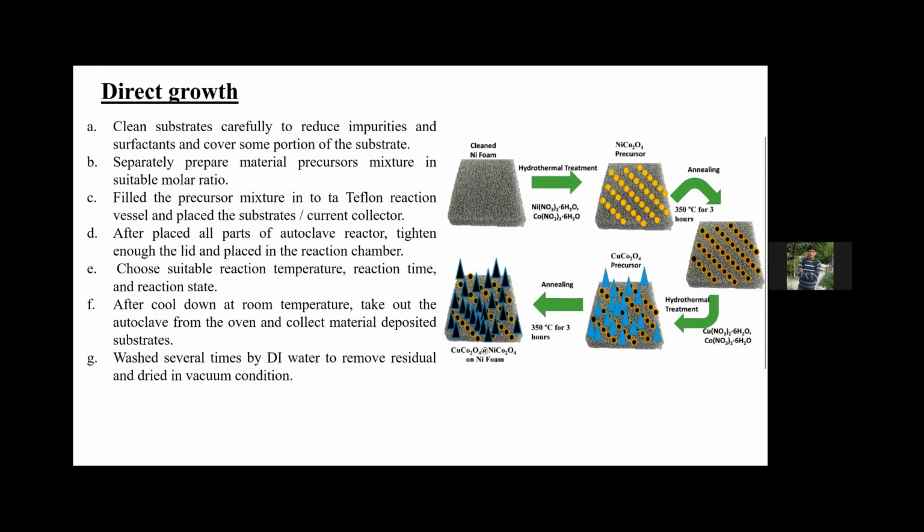So during the measurement, if we want to calculate the specific capacitance, volumetric capacitance, or mass specific capacitance, where the unit must be farad per gram, then we need to take care of this. Otherwise, to prevent this, some people use carbon cloth as the substrate, which can reduce this mass loss or the reaction between the precursors and the substrate.